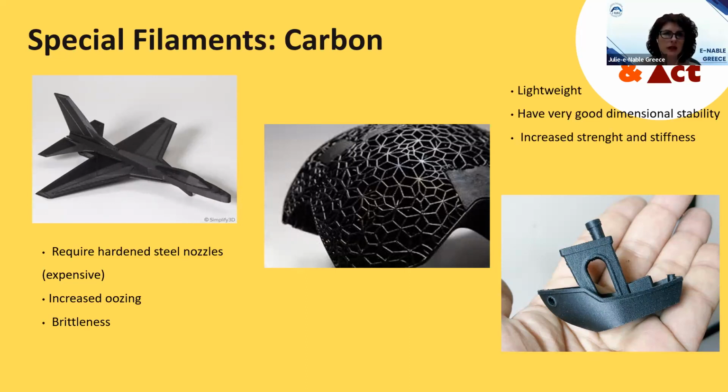This is the metal, the carbon filament, which is very lightweight, and it actually has great results when you put it in your 3D printer. You must be very careful where you buy this kind of spool of filament, because if it's an old one, it can be very brittle and break inside your nozzle and create problems for your 3D printer. If you choose a good spool, you won't have these problems and you will get this kind of surface, which is very appealing. Marcos, if you're ready, you can.